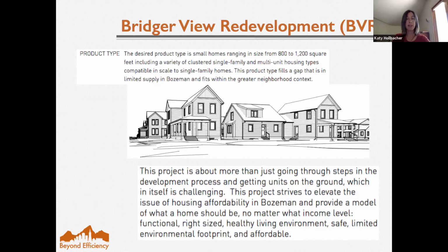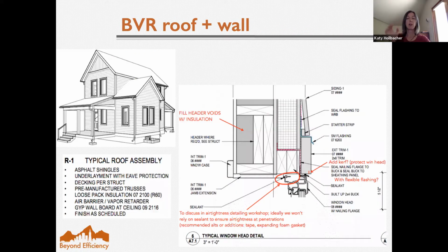And there's been really great team collaboration between ownership and architects, structural engineer, contractor, to assess a wide variety of approaches for things like attic versus cathedral roof, panelized walls, stick framed, different materials. And where this has landed is that these will be vented attics, which is just significantly less expensive to get to a high level of performance, rather than doing, say, 6 inches of cork outboard of the sheathing, which otherwise could have been a great solution, but very expensive.